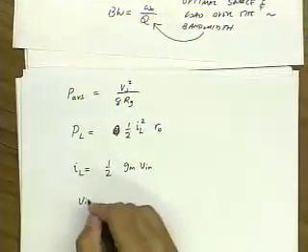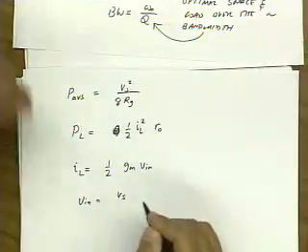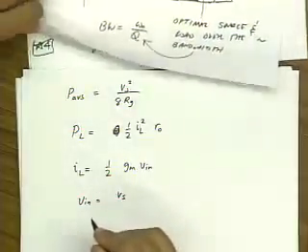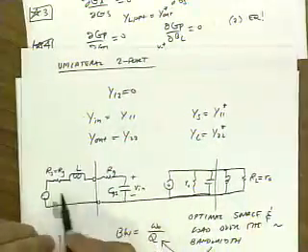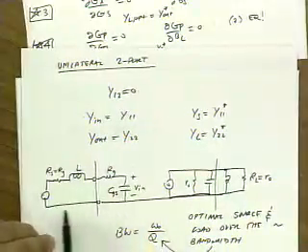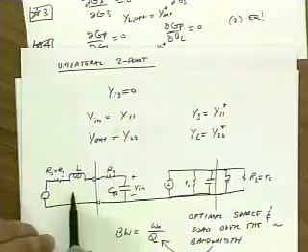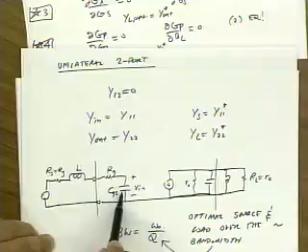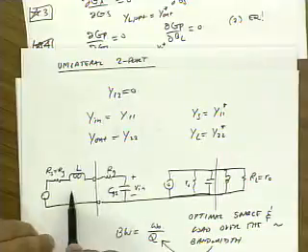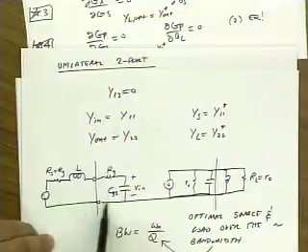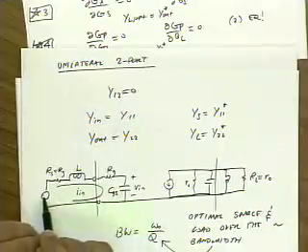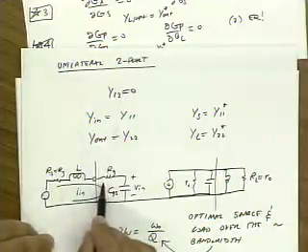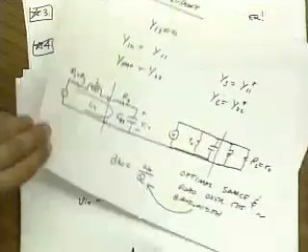Well, V in, it's a series resonant network. So V in, which is here, is equal to this voltage divided by this series RLC impedance. Well, again, at resonance, this cancels out with this. So V in is this current flowing in this loop, I in, which is simply Vs divided by 2Rg times this reactance.